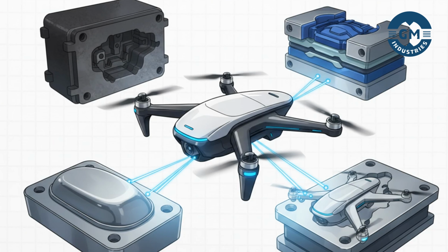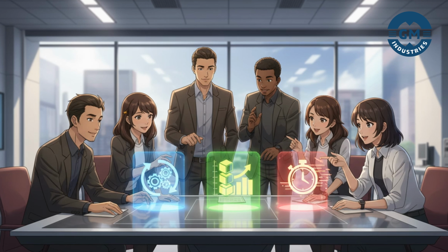And this is probably the most important thing to remember. There is no single perfect mold for everyone. So instead of looking for the best mold, engineers focus on finding the right mold. And what's right is totally determined by the product itself. The right choice really comes from answering a few key questions about your product. What's its shape and what does it do? How many do you need to make? 10,000 or 10 million? And how fast you need them? The answers to those questions will point you straight to the optimal solution.